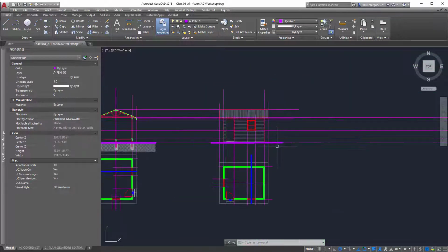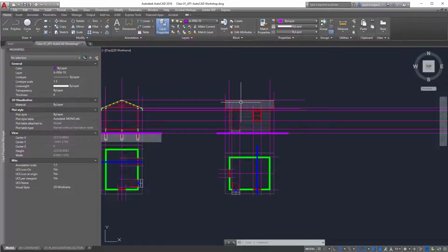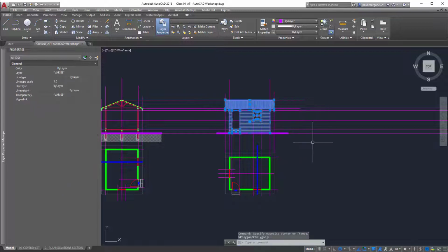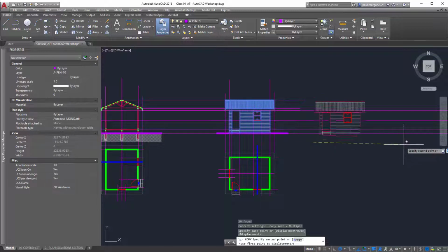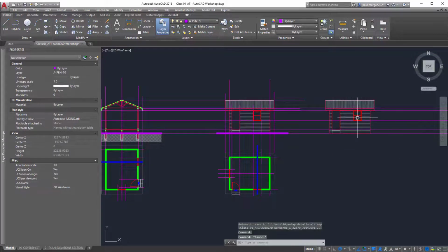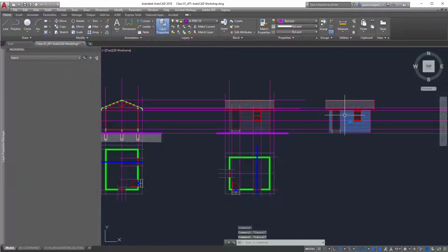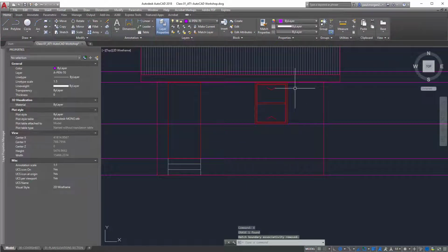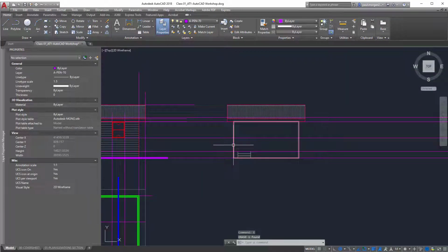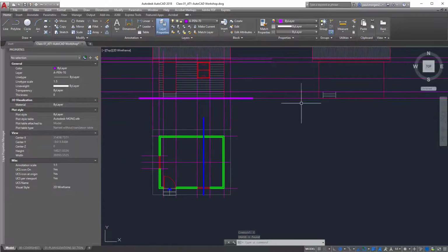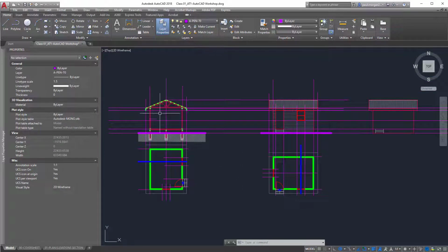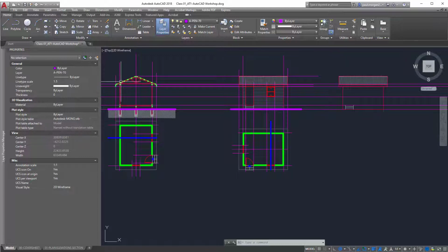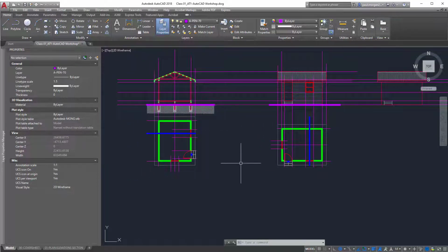Okay. Now the same thing can happen again. I mean, you can take this elevation and basically copy it across, and all you need to do is delete the window, delete the hatch, delete the door, and then rehatch it, and then you immediately have your back elevation. And then as for your left and right elevation, you could trace the section and copy that across, at least just the outside, just to make sure you've got like the ridge and the roof line right.